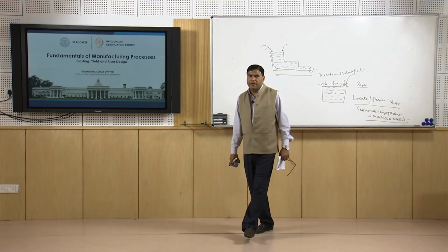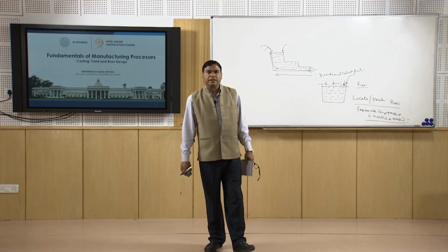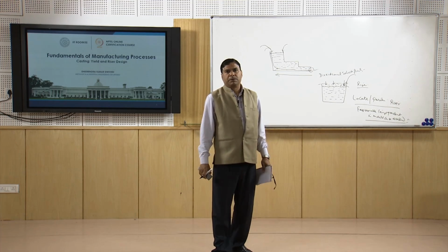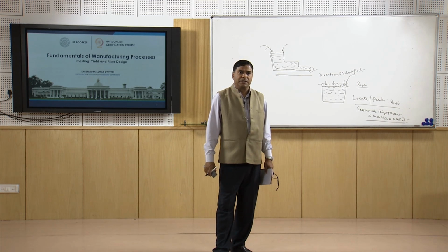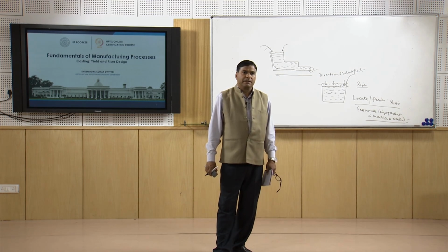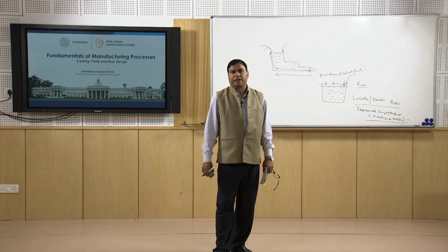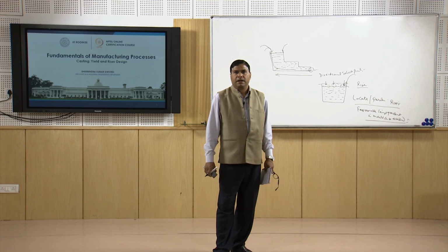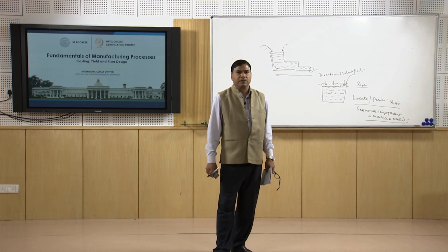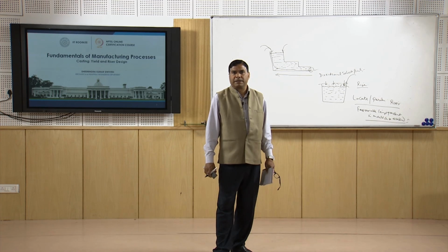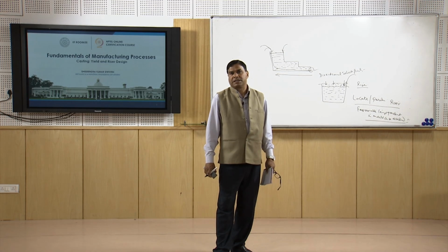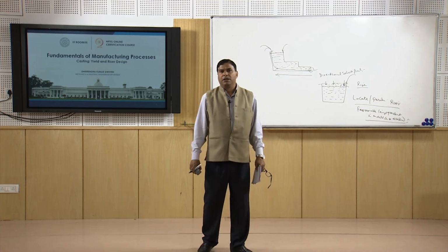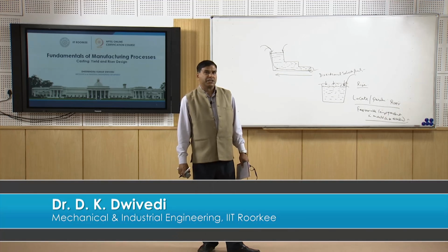So, now here I will summarize this presentation. In this presentation, I have talked about the casting yield, which shows the economics of the foundry industry, and also I have talked about how the solidification takes place in the castings, and how we can regulate the solidification pattern in the castings in order to avoid hot spot formation in the interior zone of the castings, which will eventually lead to shrinkage cavities.